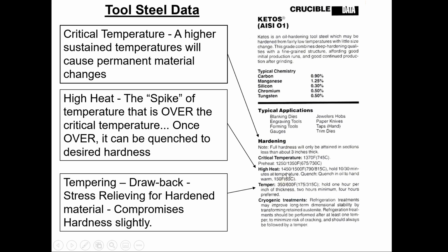You're not going to just drop it in there. You're going to drop it in and do figure eights, and keep it moving until the temperature comes down to the point where you pull it out. If you pull it out and it's still smoking, put it right back in there. Keep it going until you can pull it out and touch it with your bare hand.